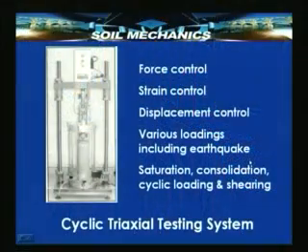Suppose you take earthquake as an example. Then the load due to an earthquake can be considered to be somewhat cyclic in nature. It is repetitive, and therefore, if we want to really understand the effect of earthquakes on shear strength of soil, we must conduct the triaxial test under conditions of cycled loading. Cyclic loading must be possible. So, this equipment permits precisely that.